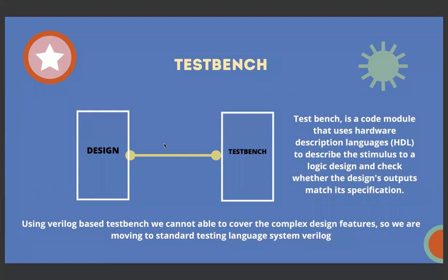So you try to simulate, try to check the use case of the design in some aspect and see whether the design is behaving as per intent or not, as per spec or not, and then you confirm things like whether everything is as expected, or if you give some nondeterministic condition, how the design behaves. So there are different aspects to it which you'll be testing using a test bench. So basically the test bench is the thing that you use to actually verify and validate the design.